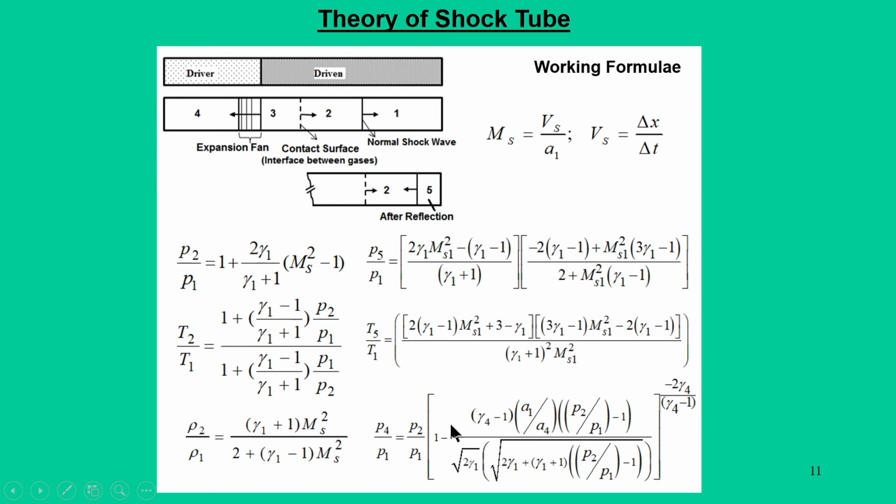So, through this process, the shock tube condition of generating Mach number can be controlled by first choosing a lower molecular weight driver gas. We do this because if you take a lower molecular weight gas, the shock Mach number will be higher. And in fact, P 4 by P 1 is nothing but your rupture pressure, that is decided by the strength of the diaphragm.